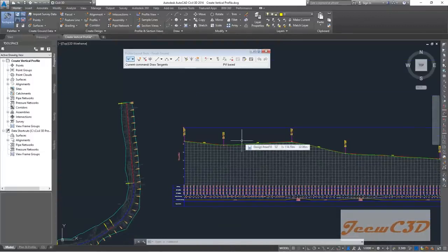But in this you have to follow a lot of things. You have to check the vertical-horizontal coordination, but we don't have that much time to check all these things. What I am giving you is a small idea about how to create the alignment. When you are designing the alignment in a project, you have to think of all these factors: vertical-horizontal coordination, ground clearance, and whether there are bridges, you have to check the profile at those locations also.